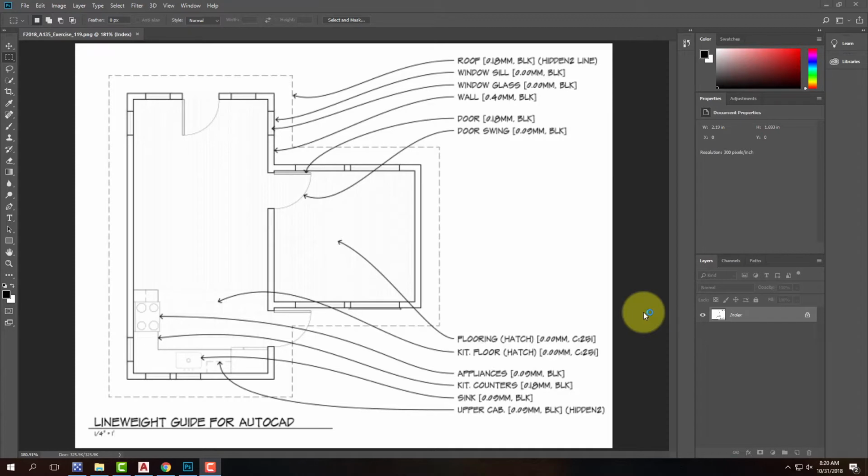Today we're going to start on exercise 119, which is a continuation of what you did last class with your floor plan. The difference is today we're going to start thinking about how do you make that floor plan readable. Thus far you drew on one layer. You had the topography layer and you had layer 0. You drew your floor plan with all of its lines on layer 0, and we're going to try to modify that such that we get some reasonable line weights, reasonable depth to the drawing, and really be able to understand what is wall, what is door, etc.